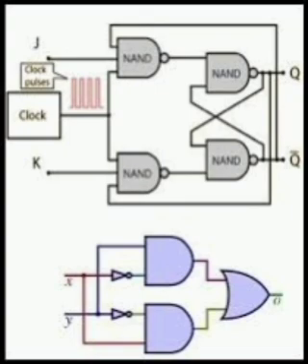Full adder performs the arithmetic sum of 3 input bits, that is the addend bit, augend bit and carry bit. Logical expression: sum S equals A XOR B XOR C, carry C equals AB plus BC plus CA, that equals AB plus C into (A XOR B). See, sum S equals A XOR B XOR C, where carry C equals AB plus BC plus CA, that equals AB plus C (A XOR B).